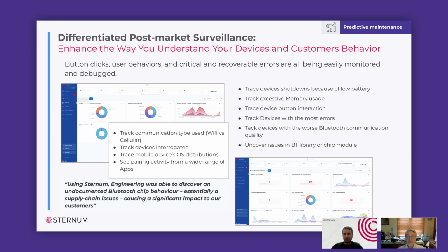And so we put traces in the system to monitor whenever the utilization goes over 85%. And so we've already gotten feedback on that, where there are some cases where we needed to go back and increase the task stack size. And this is in firmware that we've been using for over 5 years, and we never had the observability to see that. And like Lian, you had mentioned, going on to another thing, the button presses are of interest to